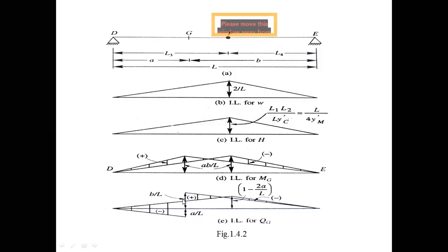So all of you draw the figure. First draw figure A, and then you can add one by one how to draw the influence lines. Let us recall from the derivation what the equation of W is. Put a heading and leave space separately. Draw the figure separately on one paper and put a heading: first, influence lines for W.